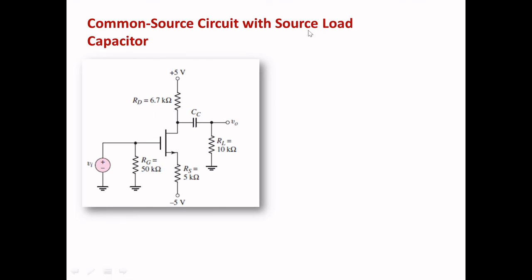source load capacitor. Okay, with source load capacitor. So this is going to be already discussed with the input, and this with your output capacitor. Okay, this is going to be a short circuit, already you know. Just we will draw the model. So very simple. First you put your common terminal, that is your source, and input terminal is the gate and output terminal is your drain.